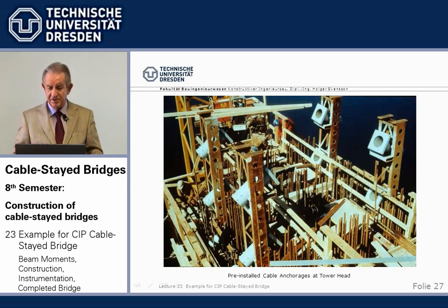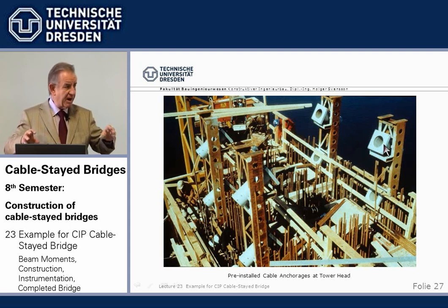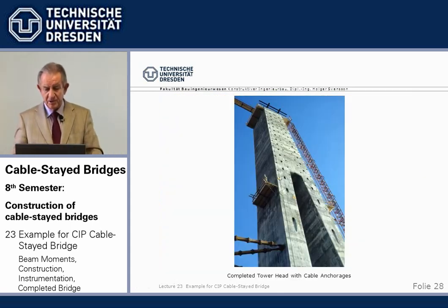So what we did is we proposed, and the contractor built, steel frames from channels in this instance, where the steel pipes were rigidly welded. And these frames were put section-wise, one on top of the other, and the reinforcement was installed around. So whatever happens, we have a rigid steel frame into which the steel pipes are welded, and they cannot shift whatever happens during casting.